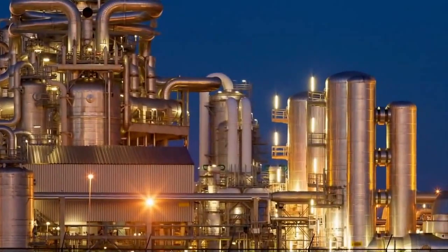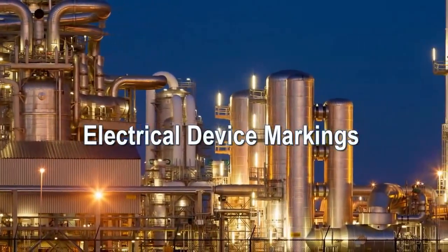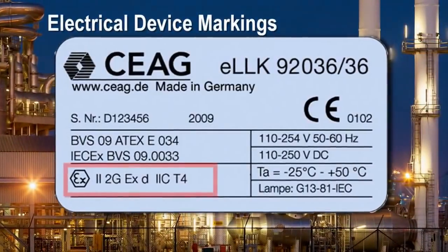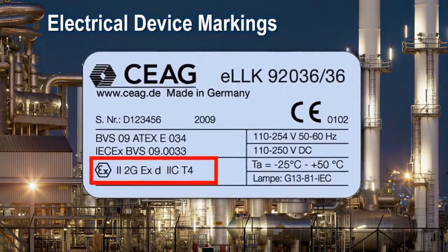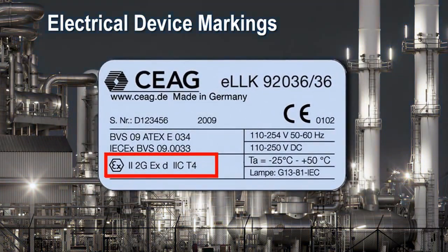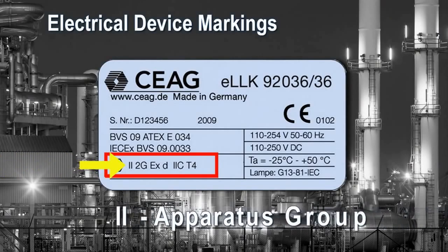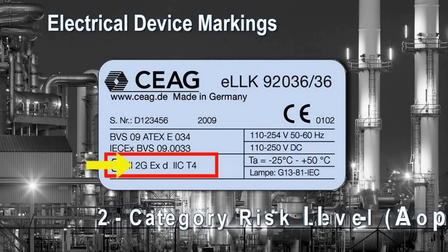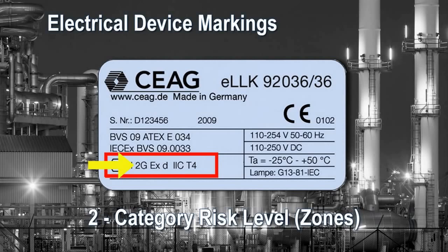All equipment certified for use in hazardous areas must be labeled to show the type and level of protection applied. In this example, we will review a fluorescent light fixture within a hazardous environment. The first identifying mark will reflect the apparatus group by hazardous application. A 1 would indicate usage for coal mines, while a 2 would indicate general industrial environments. The next identifying mark is the category risk level. As mentioned earlier, there are 3 category risk levels that would identify the occurrence of an explosive combustible material.